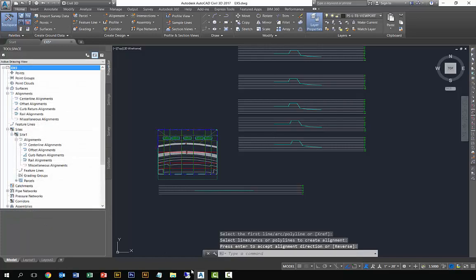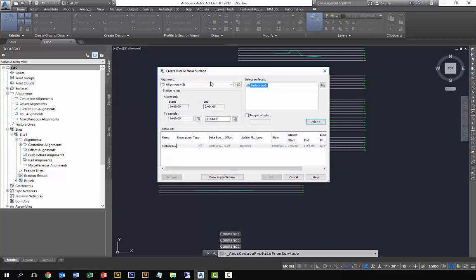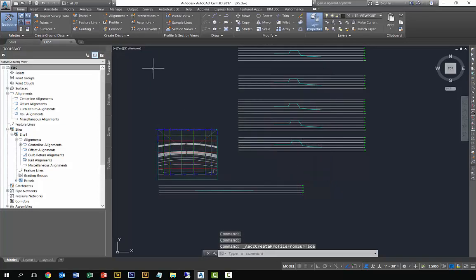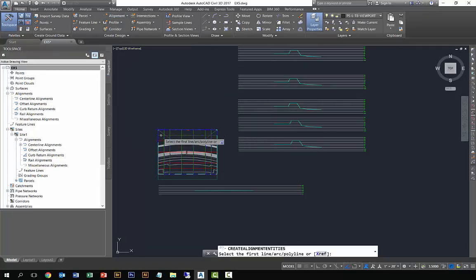So, when you're setting up your Create Profile View, make sure that both the cross sections and the longitudinal sections have the same base, which should be -20. This will make it easier for you to create the sections in generic AutoCAD to make the model.